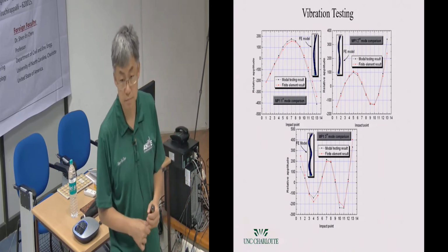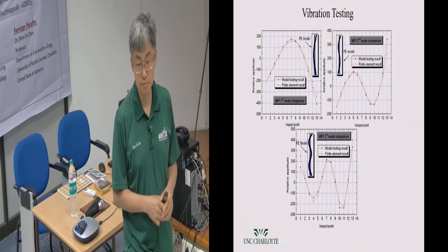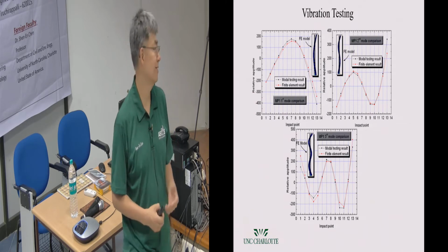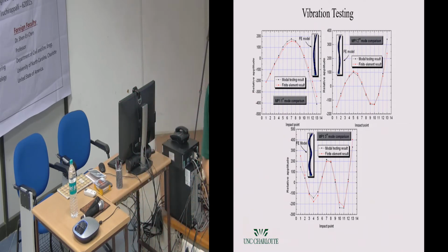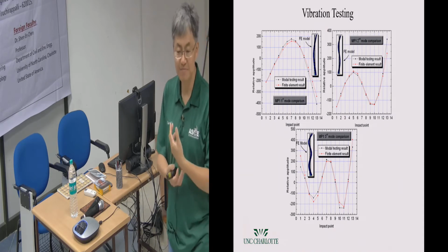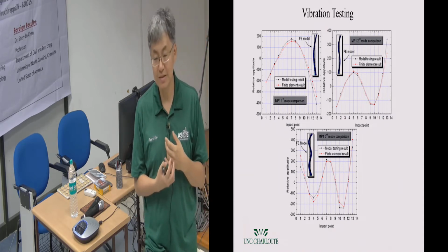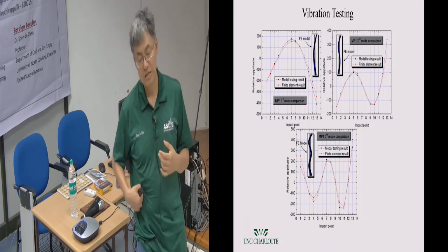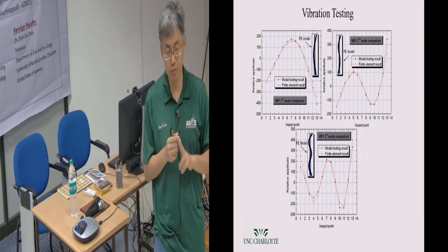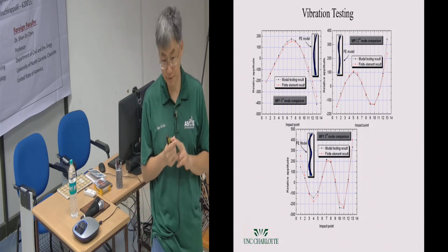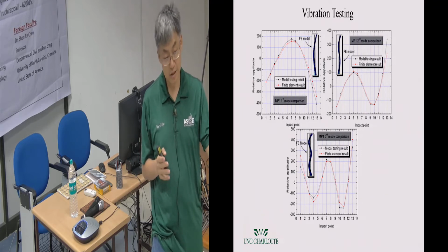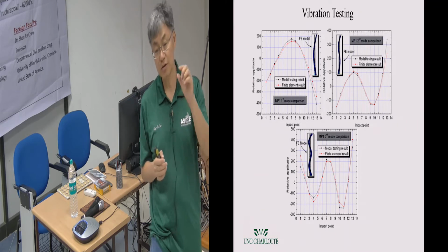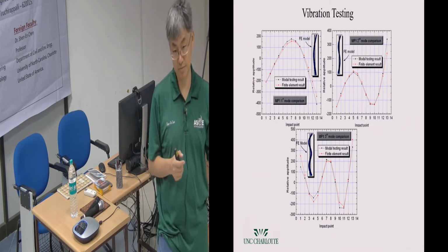Is the model testing result more reliable, or is the finite element result more reliable? It is almost the same. But all finite element results cannot be the same. No, cannot be. So we have two techniques. One is called model updating. You have your actual experimental results, and then you update your finite element model so that you can get the right material property.